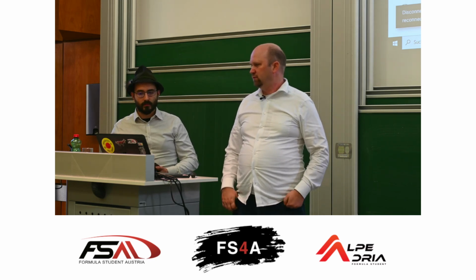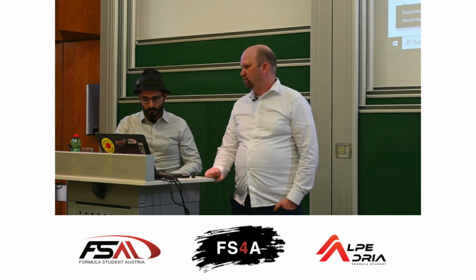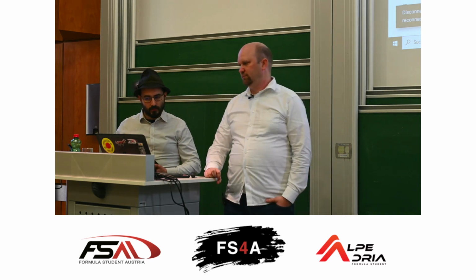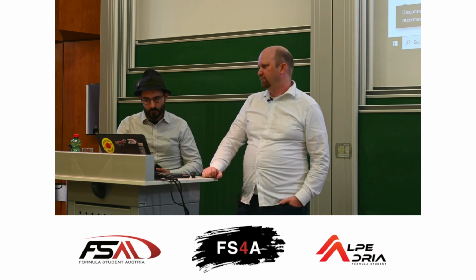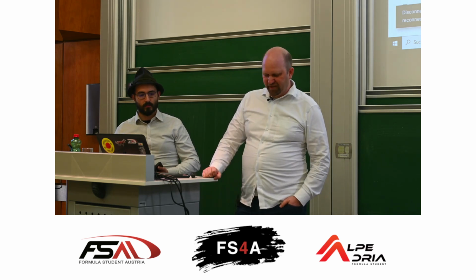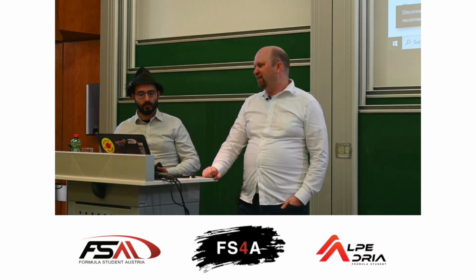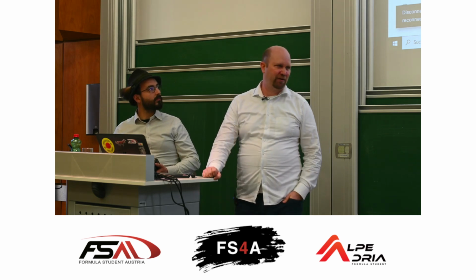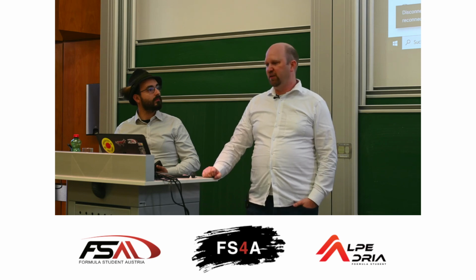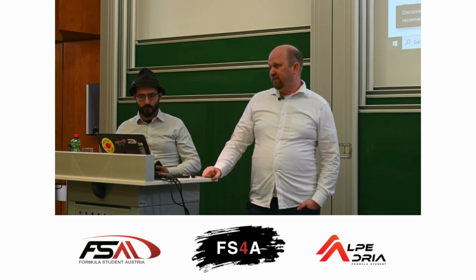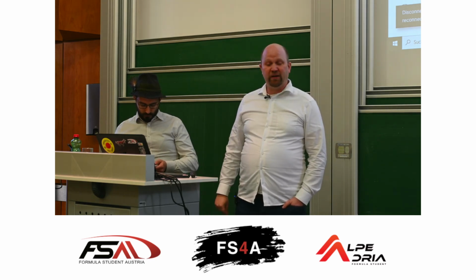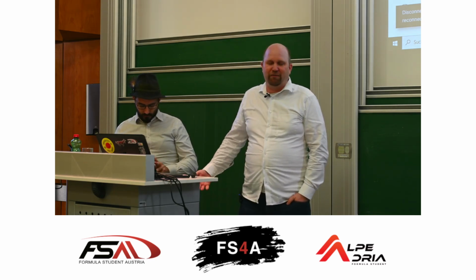Can the TSAC have cooling holes on the structural wall facing the driver, so through the firewall, if it has ducts made out of fire retardant material that is mounted on the same wall and redirects the holes to the sides away from the driver? That's always a question of definition. When your ducts are part of the TSAC, it's allowed. So if they are always mounted, if they are glued or something like this, then they have to be made from material that the TSAC can be, so fire retardant material and so on. So if you do it the right way, yes, it is allowed. If you do it the wrong way, it's not allowed. Quite simple.